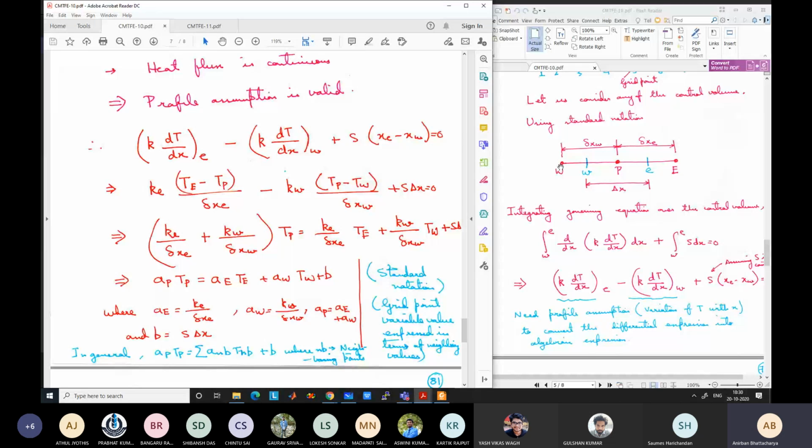Okay, generally it is stored in terms of vertices. So for example, here the control volume has two vertices, small w and small e. So in terms of these vertices, if I store the vertex values, I can always calculate what is the grid point location, because it will be the centroid. So it will be halfway between the vertices. Okay.